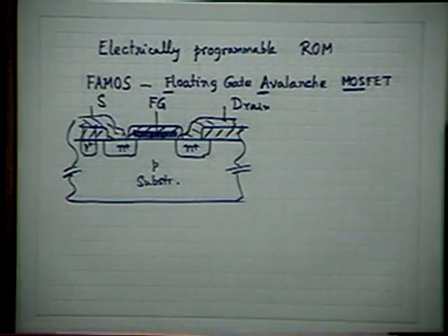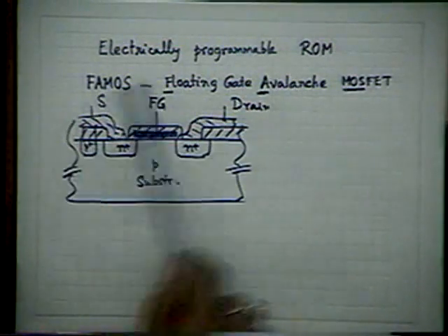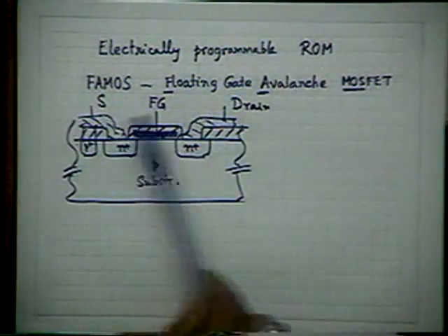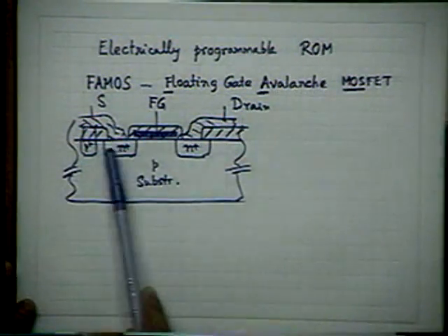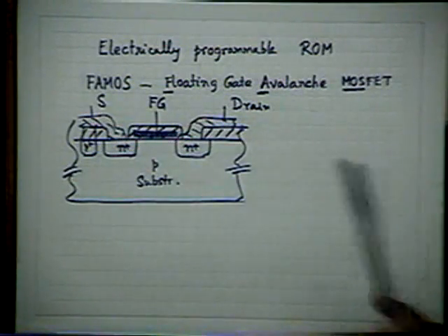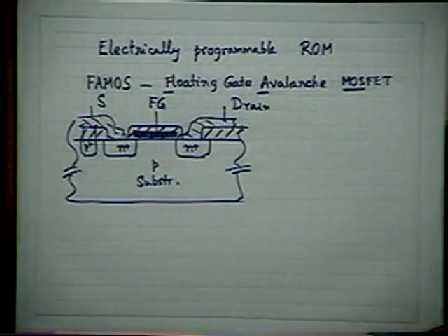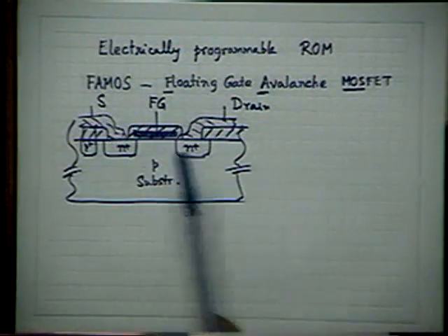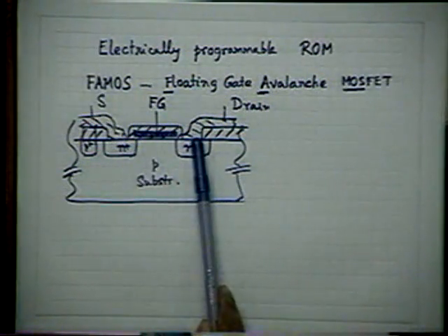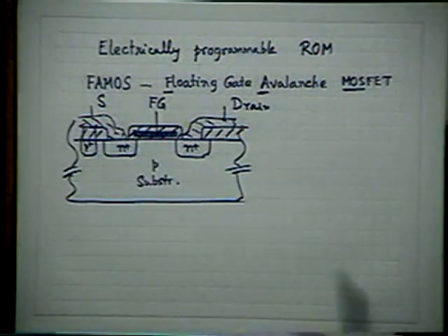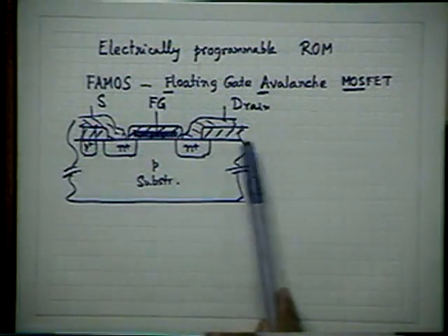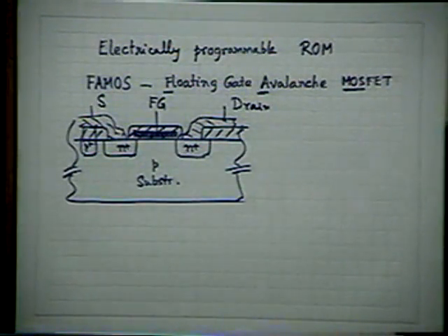Is it all right? Have you understood what I said? For normal operation, suppose it is 5-volt operation, that is okay. Up to 5 volt, this device remains on because it has been designed to be working under depletion mode. That means there is always an inversion layer. Under normal situation, there is an inversion layer which connects the source and drain. Therefore, the device is on.